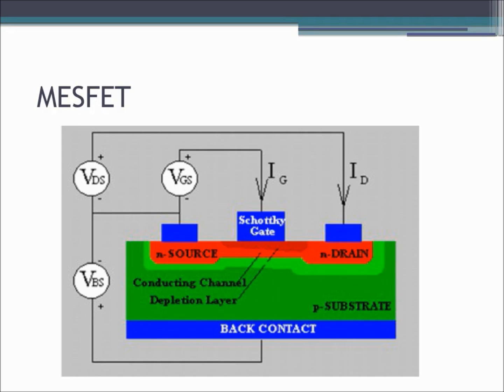This turn-on voltage is typically 0.7 volt for GaAs Schottky diodes. The threshold voltage therefore must be lower than this turn-on voltage. As a result, it is more difficult to fabricate circuits containing a large number of enhancement mode MESFETs.